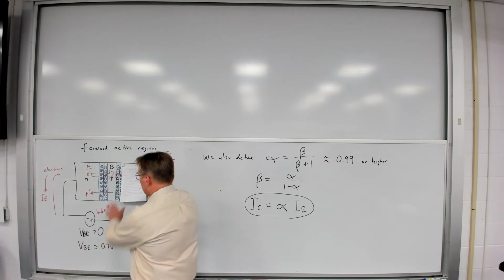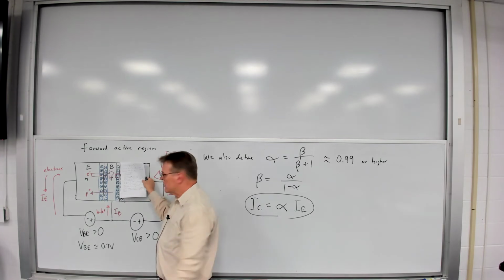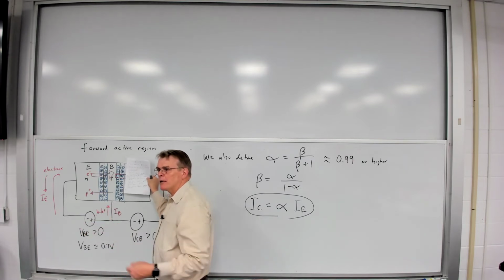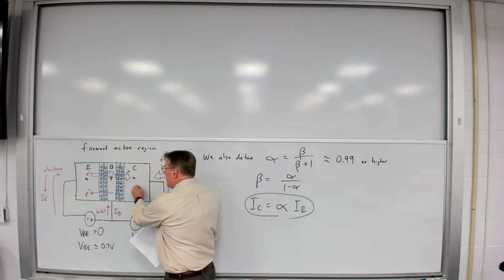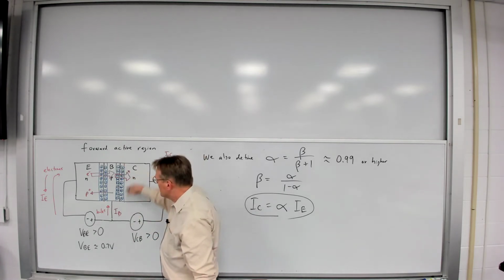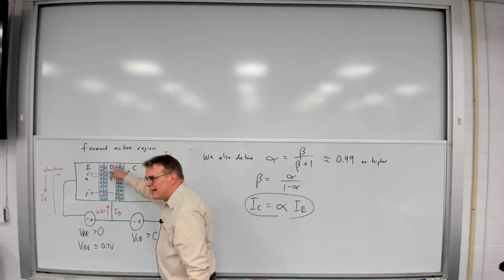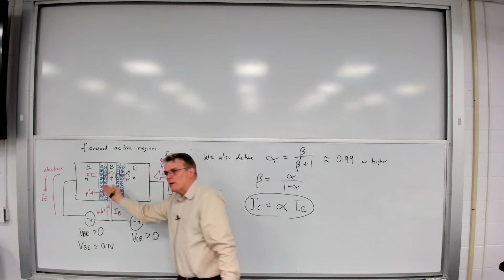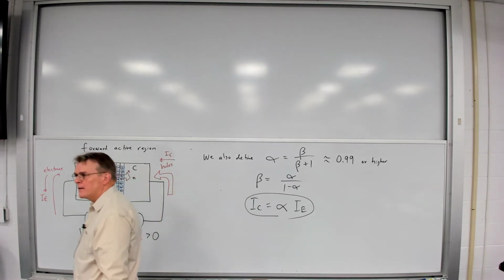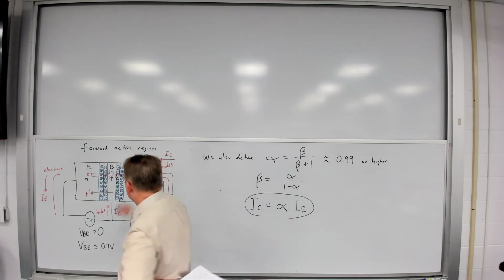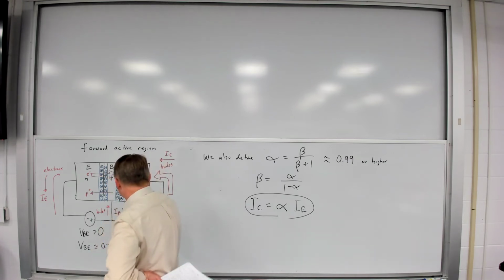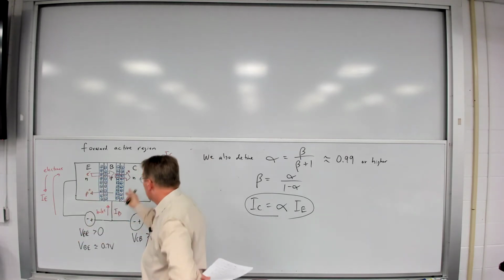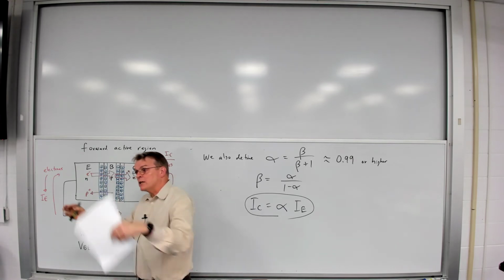So this is nothing more. If you just look at this right here and just ignore the collector region, that's a PN diode. We already analyzed that PN diode. That is no different than what we talked about a couple of weeks ago. The only difference here is now we're adding on that collector region. We got a reverse bias region, and the excess electrons, which turn into minority carriers in the base, can be captured by that collector, and they can sweep across that reverse bias junction. The collector is going to capture these electrons in this N region because we're able to supply holes from this source here in order to cancel those out. So the holes and the electrons are going to annihilate each other.